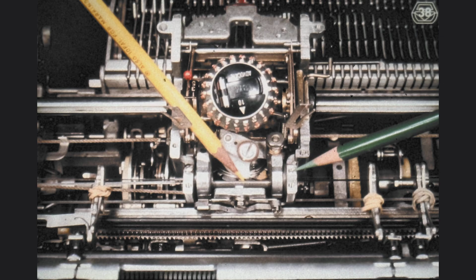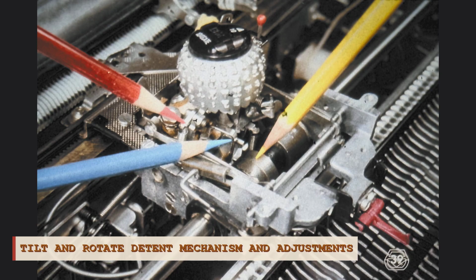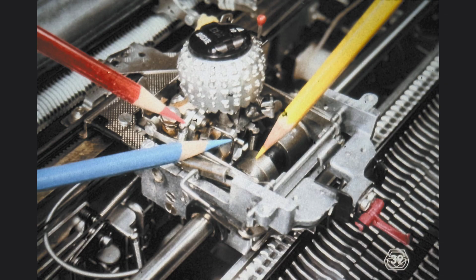Consider that the element sitting on top of the rocker needs only to be rotated and/or tilted in order to turn up with the correct character. We explained earlier that we need to firmly hold the element in position at the time of printing, and that all of the adjustments which deal with holding the element at the time of printing are the fine alignment adjustments. The sequence we have to follow to take care of the alignment adjustments is extremely simple. We start with the carrier and work our way up to the type element.